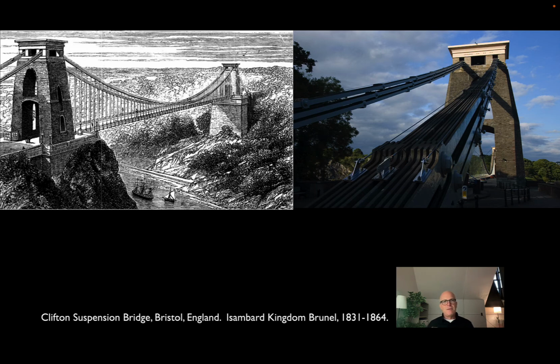These two methods, right, arch bridges and suspension bridges, go some way to solving the fabrication problem. You can build a bridge out of a lot of small pieces, ship those to the site, and put them together. But they rely on, in the Saltash case, very careful calculation, right? Tuning the arches very precisely so that the thrusts cancel one another out. In the case of the suspension bridge, an awful lot of work goes into getting the towers up high enough, the compression structures up high enough, so that you can make the tension system work.